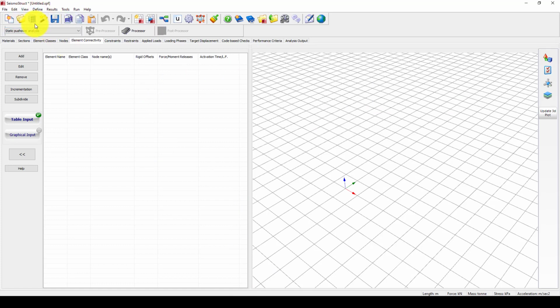Here is called the time history stage or load cases, which starts from 0 and ends at 40 seconds, and it's a total of 400 steps, and each step is 0.1 second. You can also edit it in case you want to reduce the analysis time. You can take 20 seconds or less, or even increase it.